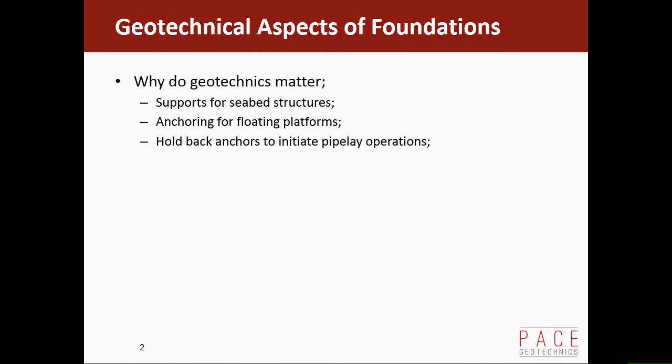Today, the exciting subject of foundations, what they are, what they do. We're only really going into any detail on subsea structures, where we're looking at structures for supporting pipeline end manifolds, valve housings, etc., things like that. They also anchor floating solutions, which I'll talk about, because any project you're on will probably have either a platform or some sort of FPSO. And then the other important area for foundation solutions, or a variation on foundation solutions, is anchors to actually hold the pipeline as you start your lay. So at the start of S lay or J lay, you need an anchor of some description, simply to hold it back on the seabed.